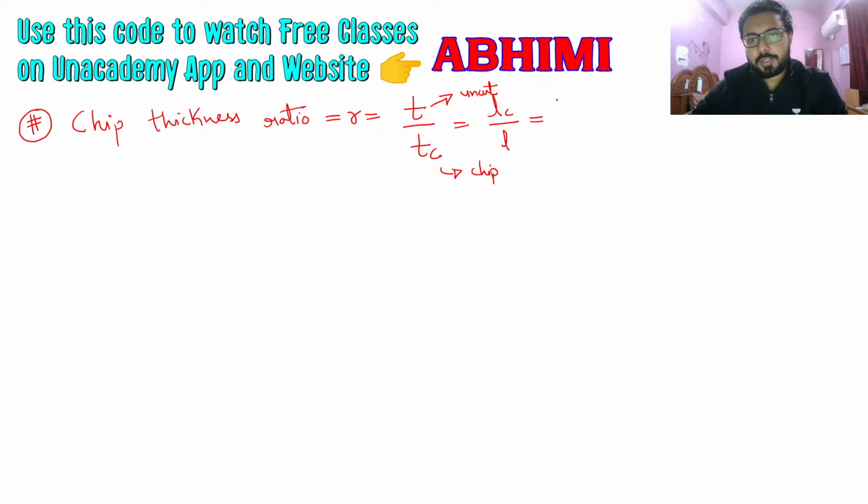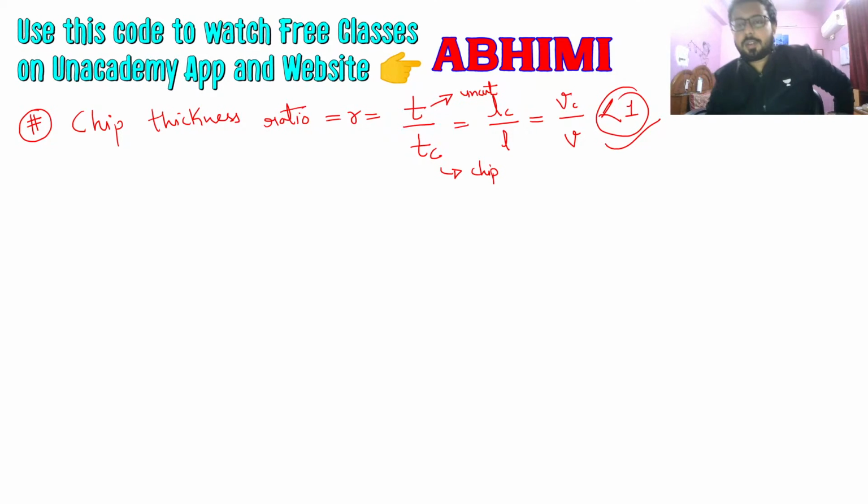And then we have the chip velocity divided by the cutting velocity. This will always be less than 1, because due to plastic deformation your chip thickness will increase, therefore your denominator will increase, and you will get this ratio less than 1.